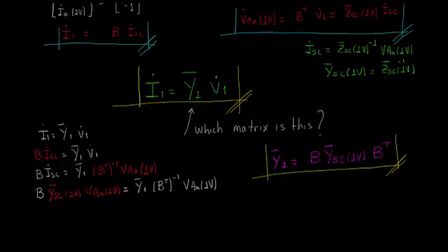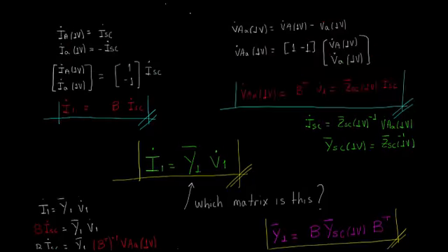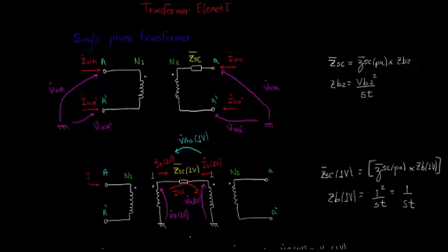There is no wiring connections represented, pretty much like a per unit model, commonly used for positive sequence power flow. Now let's include the windings. In order to do so, let's equate the currents injected in each node of the initial single-phase transformer model with the injected currents in the short circuit reference frame, I1.